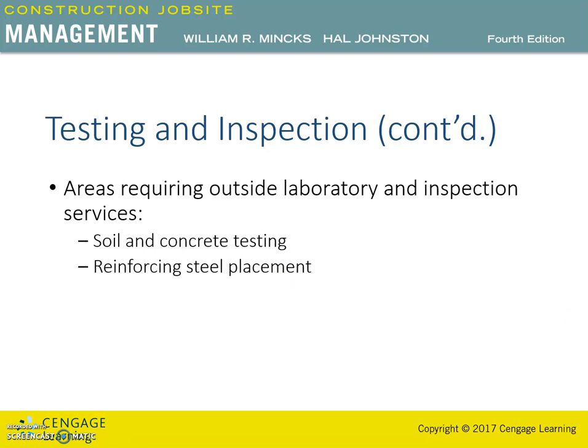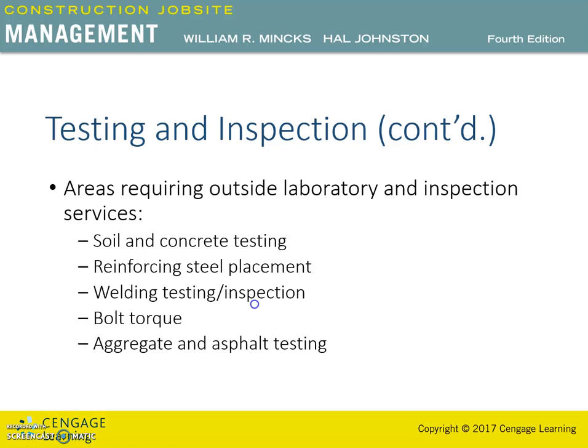For the reinforcing steel placement, confirmation of the placement location. For welding testing inspection, it will be the visual and X-ray testing. Bolt torque, tested torque on example bolts. Aggregate testing, hardness, material composition. Asphalt testing, mix design, strength, and layout and vertical alignment is also tested.